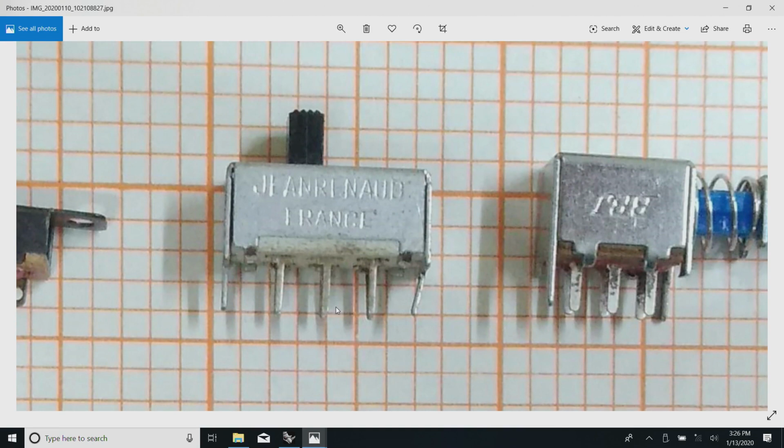Something which is reasonably related to this is, you will notice that on the printed wiring board itself there are no insulators. One side of that, depending on the type, is generally exposed, but the thing to note here is that those tracks or traces are not going to change. So, once you design a particular spacing, and a particular conductor width and all that, it stays, and if the manufacturing process is in proper control, these things will stay like that, and their behavior, especially with respect to the parasitic elements, is very much predictable and calculatable.